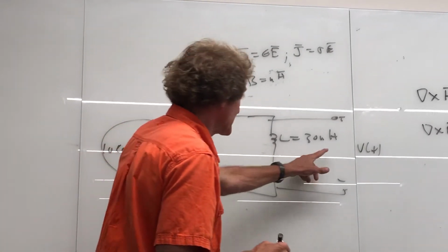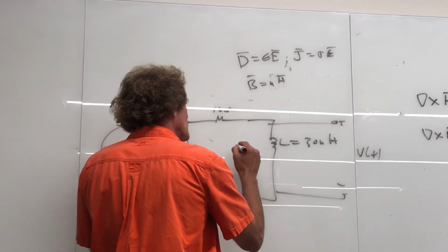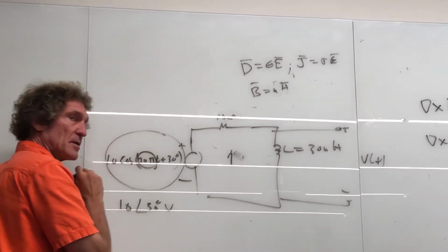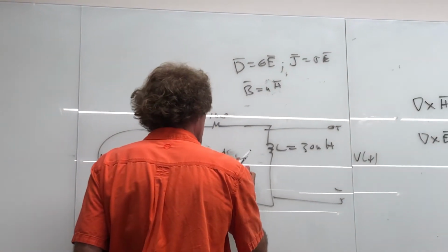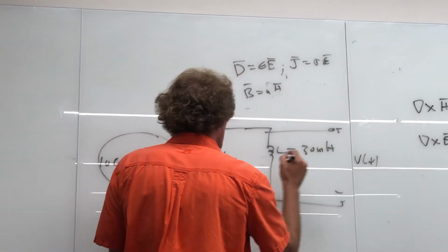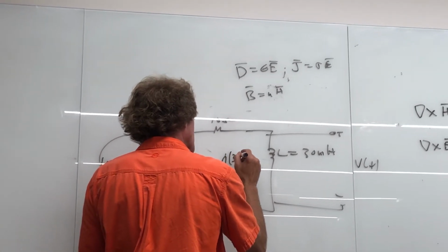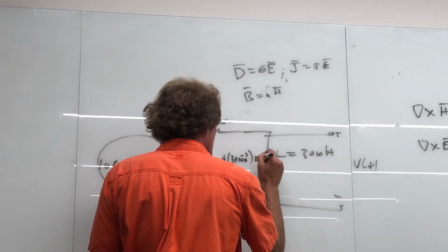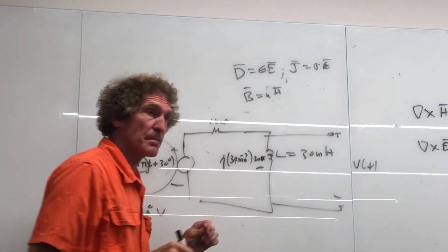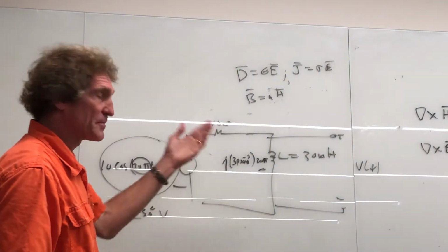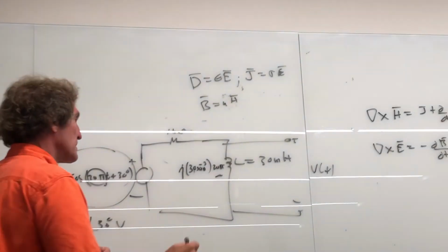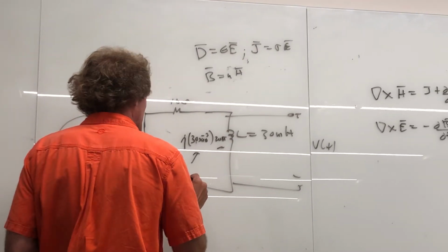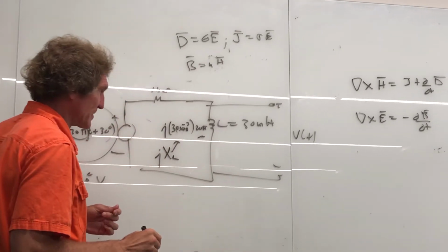And then instead of having this inductance, you would put down impedance here, which would be j omega, and omega would be the coefficient of t inside the cosine, right? So this would be equal to 30 millihenries, so it would be 30 times 10 to the minus 3, times 20 pi ohms. I don't know what that is, but it's a value, correct? Just call it jXL. So it's the impedance of that inductor.